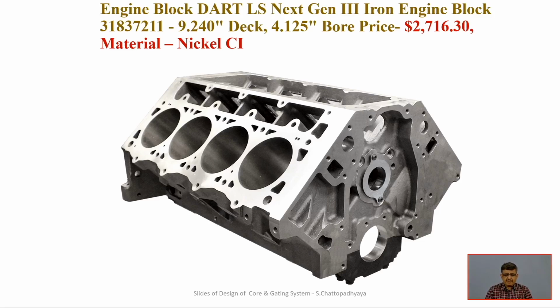So one can appreciate in the engine block how the cores have a very big role to play, so that little machining has to be carried out for the finishing activity. If the cores are not provided, there is a huge amount of machining and a huge cost associated with it. So cores are a magical device to reduce the time associated with machining of those engine blocks.